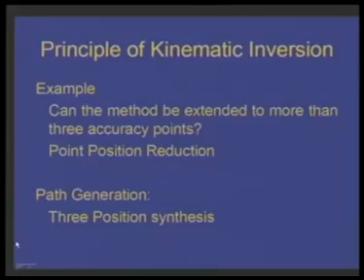We must have noticed the most important point of this graphical method is the principle of kinematic inversion. The student should note which link inversion should be done on, that means which link should be held fixed, and on what configuration. We have a choice. We can choose the inversion to be made on the first, second or third configuration.